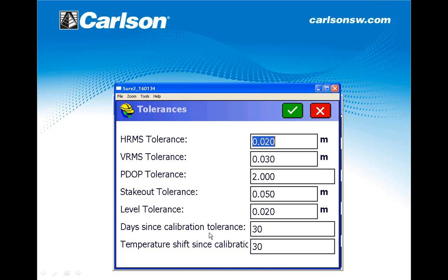Okay. This calibration, I will explain now, this is a beta version with things that we're working on for calibration of the sensors. So this is set in meters, and of course, it depends on the antenna height, right? Because at the end, tilt angle will compute a final linear deviation that is different depending on the antenna height. But you don't need to take care of that. So green check here, this is my limit, 2 centimeters, okay?